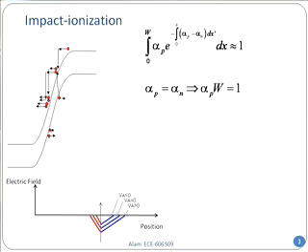Now this alpha p, what is this? Alpha p is the number of extra electrons generated per injected electron. And it depends on the electric field, because the more electric field you have, it is easier for the electrons to gain energy, right? As a result, if you look at the experimental data, people have done a lot of beautiful theory. Many famous professors have spent probably a significant part of their life looking into this type of impact ionization process, especially in the 60s and 70s. And one simple form that sort of looks correct in terms of electric field is this.